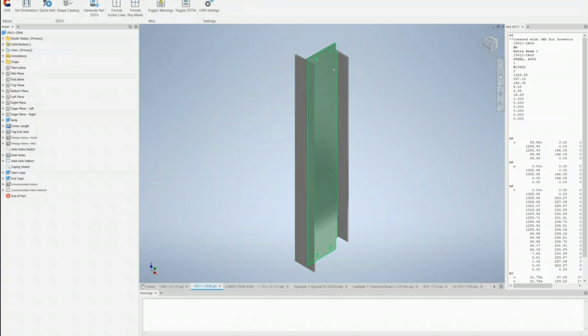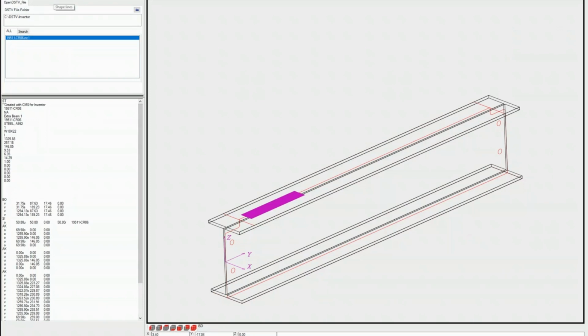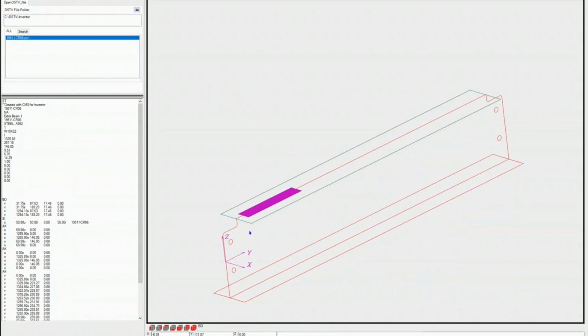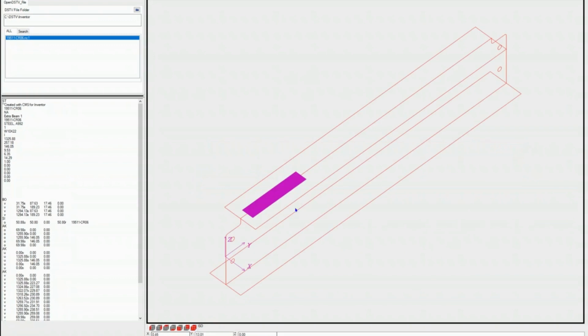So if I just compare that quickly, as I said, we had 2 clips at the 2 sides, right? And we had 4 drills on both corners in total. If I click on my shape lines to remove that, then I can see only the CNC lines here. That box over there is actually showing you the part number stamp, right? If I go to the view over here, this is where I can see the actual view, right? On the 3D view, I will see it as a black box over there. Okay, so this is what it involves to create an NC1 file from a part level.